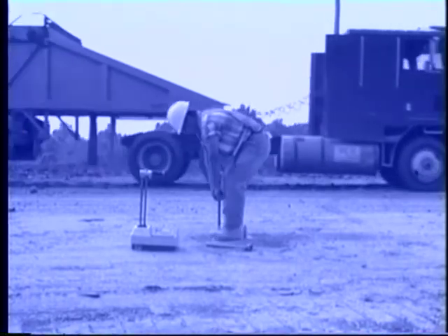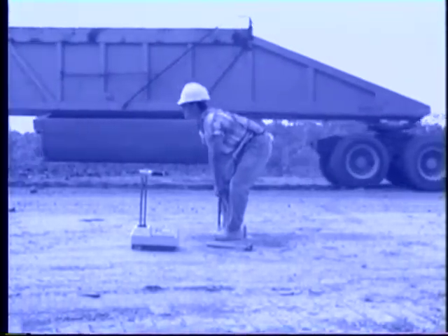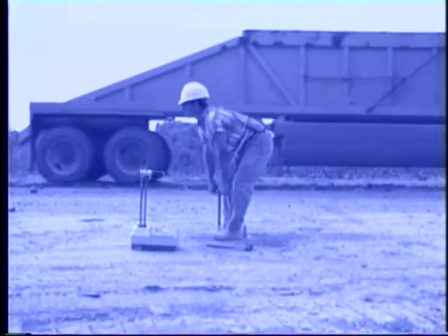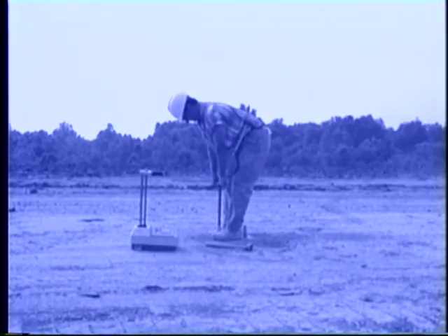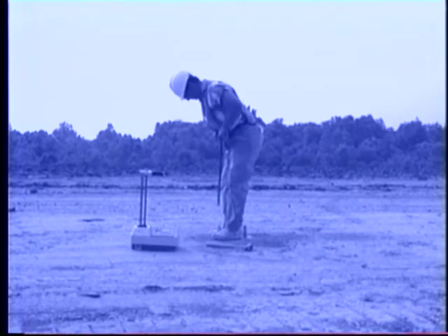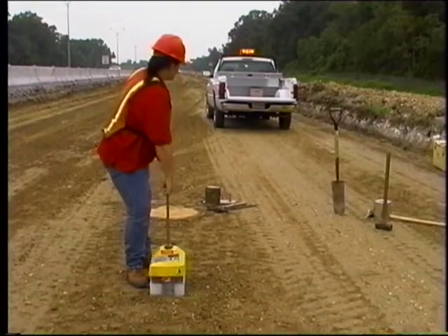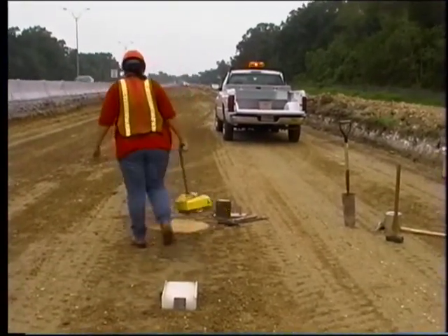Don't loosen the drill rod by tapping from side to side with the hammer. The probe hole must be perpendicular to the surface. Otherwise, as the device is rotated, the source rod will lose contact, causing test error. Place the nuclear device on the prepared area.